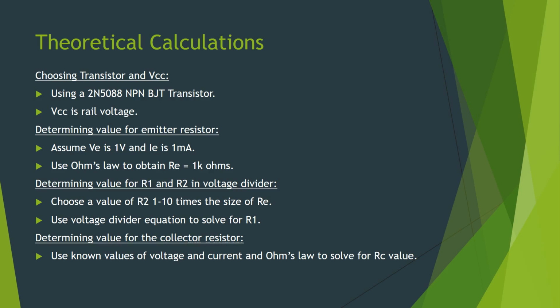the top, and we want a gain of 10. So if we wanted 10 volts at the output, we would want 15 minus 5 volts divided by the resistance, because basically we can use Ohm's law. Voltage divided by resistance equals current. We know the current and we know the voltages, so we can solve for the resistance. In this case, we find that the resistance is 10,000 ohms.